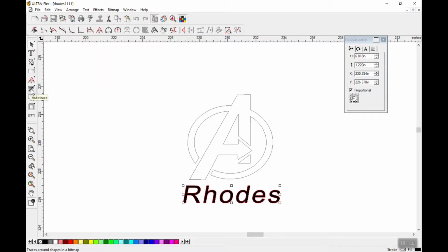Moving down, we do have an auto trace feature on UltraFlex. I would not recommend using this. If you get up to the computer and you just have an image and you try to edit it, the other students might get a little testy with you. Images should always be traced on Inkscape, saved as a DXF, moved over to UltraFlex. We really never do the weld button. This deals more with just linking images. The measure button, you should be measuring the vinyl, not the image.